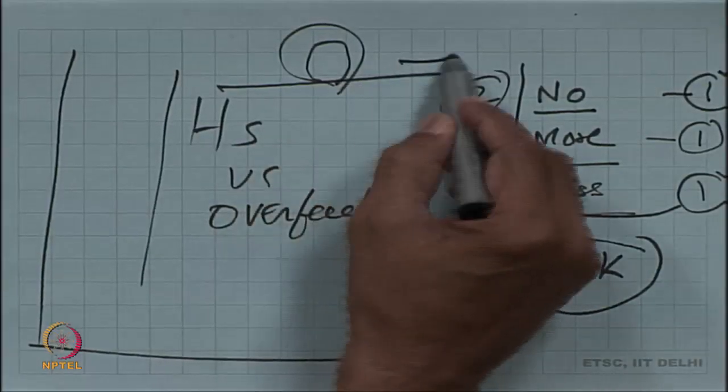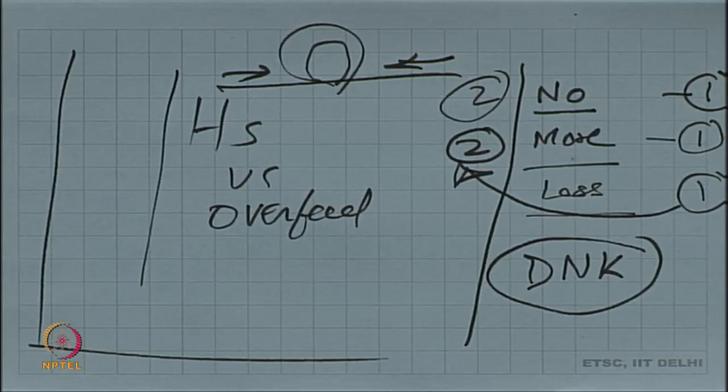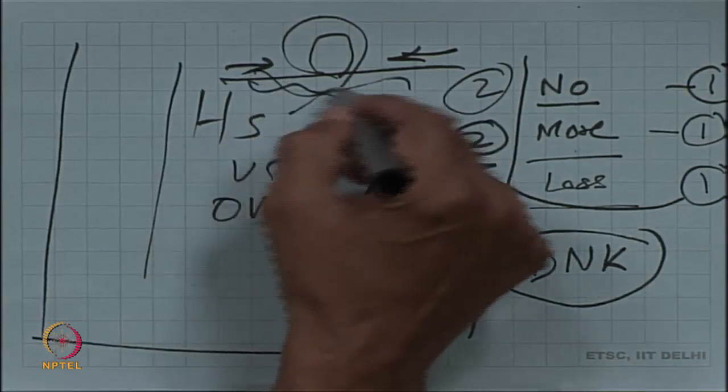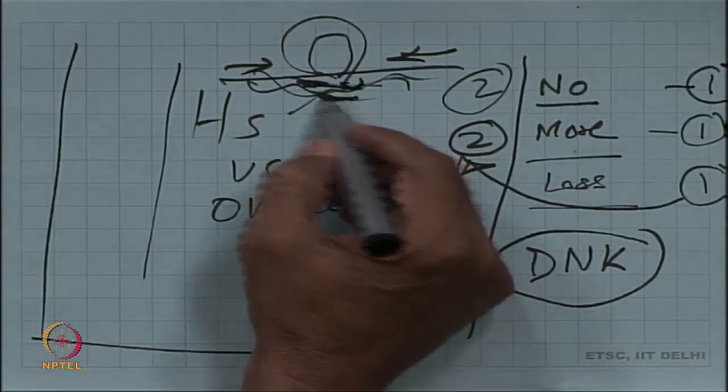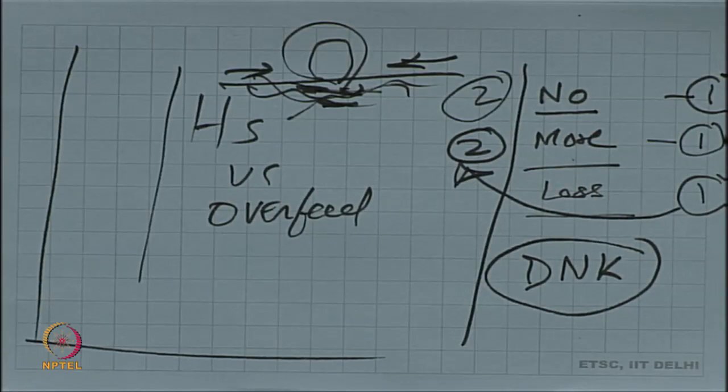The ones which are in the loop, part of a loop can shrink. It is not going to change the length of the yarn, because the loop is shrinking, so what? But if it is tighter material with a lot of entanglements, and if this one wants to shrink, the other cannot refuse. Versus a situation, a sliver instead of a yarn lying in some hot oven, every fiber wants to shrink, but the one which is shrinking cannot force the other one which is near somewhere to also shrink. So, it shrinks its own way.